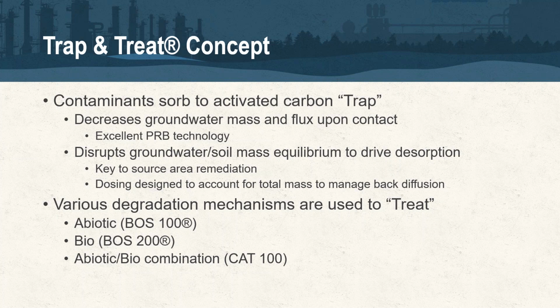So this is very similar to what we see with chemical oxidation, right? That's what rebound is on chemical oxidation sites. You treat what's available. That oxidant runs its course. It's not active anymore. Now you get desorption off of the sorbed phase to reestablish equilibrium. So it's the same concept here. The one comment that I'll make, and I'll probably make it several times here in the presentation, is that if you're trying to meet a soil standard out on your site, we have to really look at that, look at the contaminants, look at KOCs, FOCs, because obviously different contaminants are going to come off easier than others.